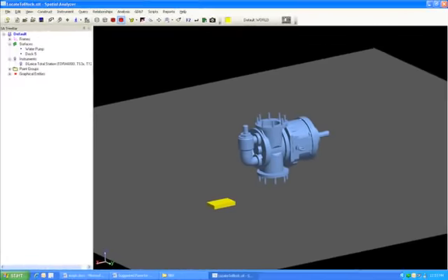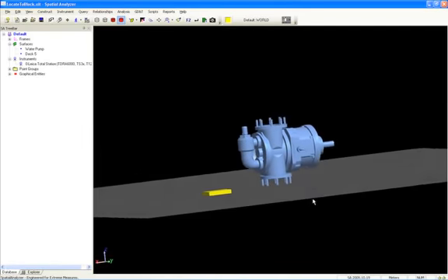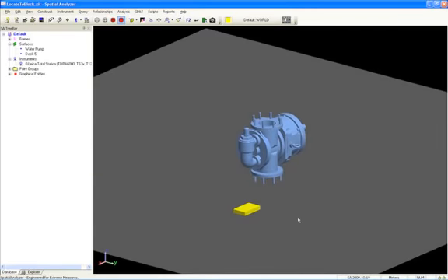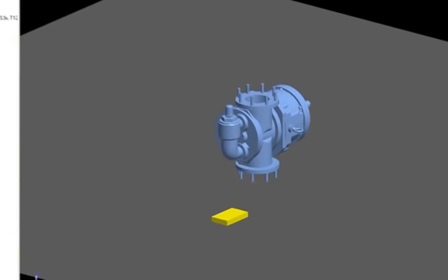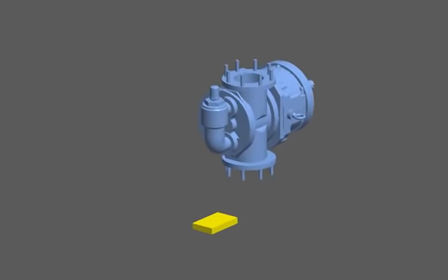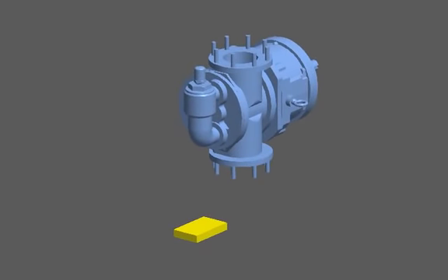It's common in shipbuilding to have a reference block defining a reference system for a given compartment or area of the ship. These blocks define the orientation of the reference system and also give a reference for a point in the coordinate system. One method to align to this reference is to use the plane line point instrument locating method.